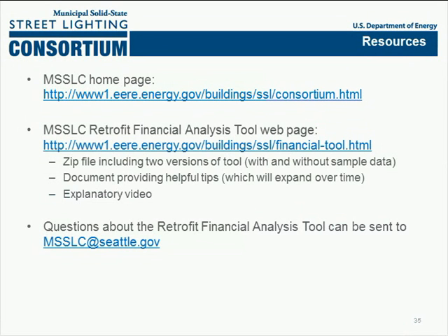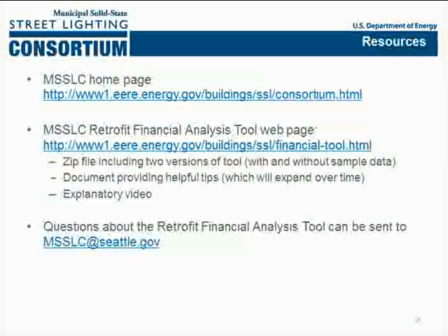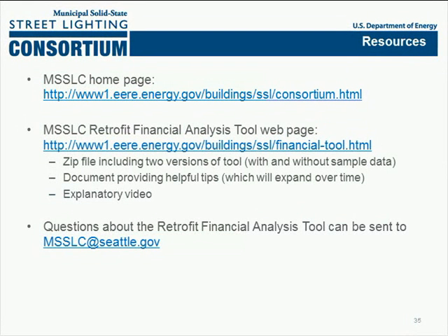And Bruce, if I could just jump back in on the previous question. There are two ways to handle a rebate. A lot of times utilities will handle it on kilowatt hours saved. In this program, on the input page in cell Q58, rebate value, it's asking for a dollar value per unit. If the utility offers it per unit, they would enter that dollar value there, but likely they would have to calculate the kilowatt hours saved per unit over the incumbent technology and then multiply that out. Say, for instance, if it's 22 cents per kilowatt hour times X number of kilowatt hours saved, then that value would go there.